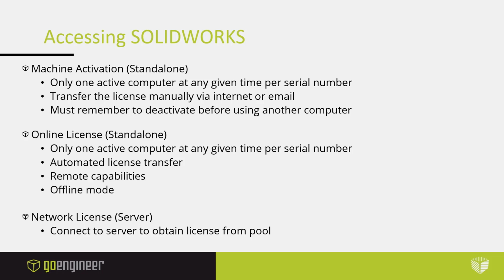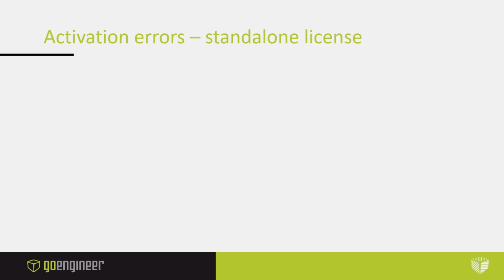Okay. One thing to note here, obviously, for the network license, for the newer versions of SOLIDWORKS, one thing we run into is having the correct operating system on the server. So you'd need at least Windows Server OS 2016 or 2019 to run the latest versions of SOLIDWORKS. So that would be 2020 or 2021. I mentioned it will also run on a client computer, so you can run Windows 10 if you need to. All right,